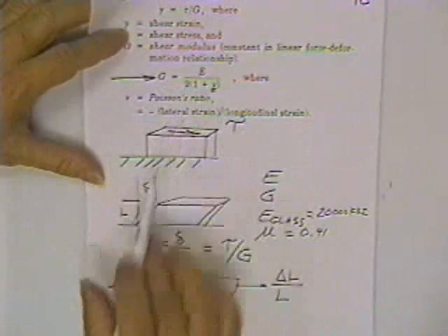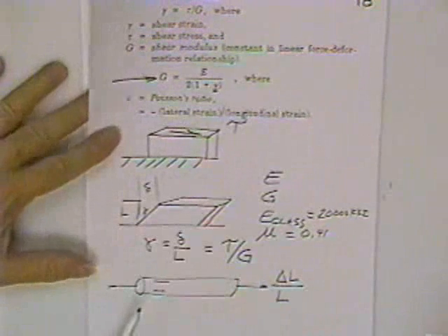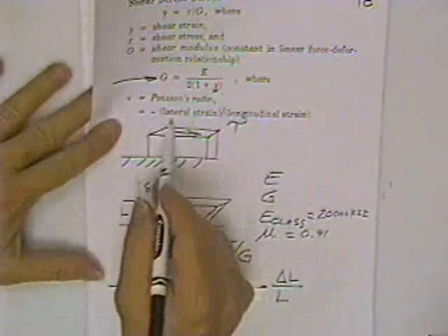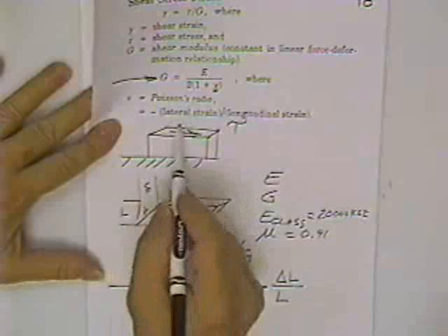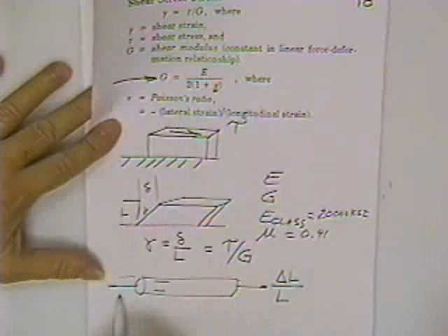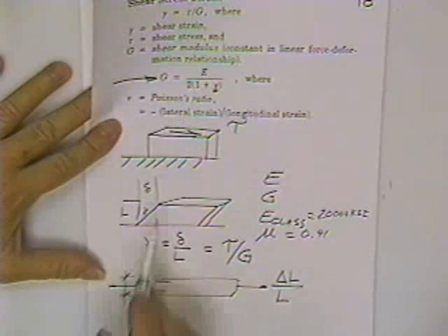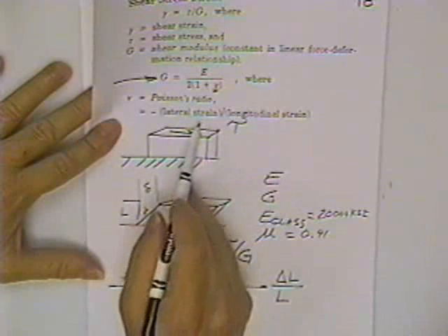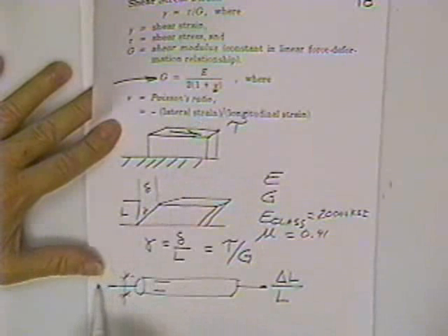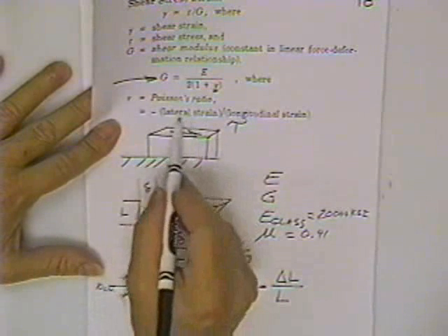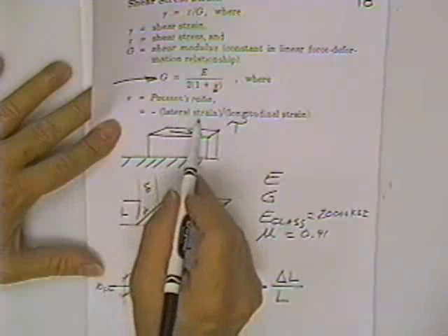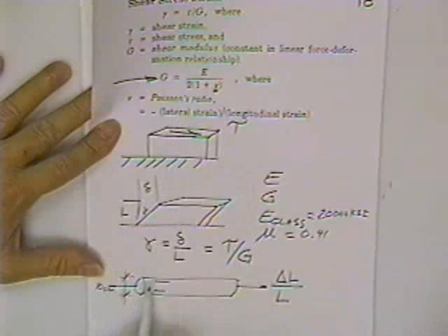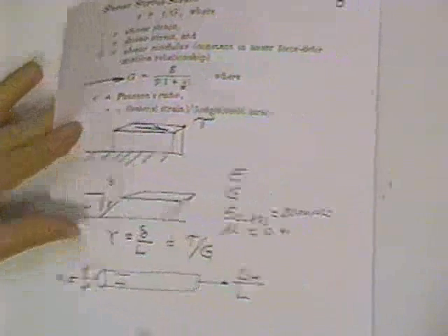You use this equation right here to get the answer. If you have lateral strain, now be sure you multiply it times how long this thing is, because the strain is like inches per inch or centimeters per centimeter. So if this was 10 centimeters across and you found this number right here in centimeters per centimeter, you have to multiply it by 10 to get the total necking down that it did.